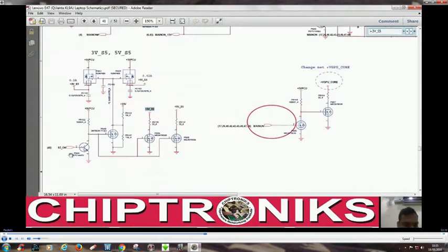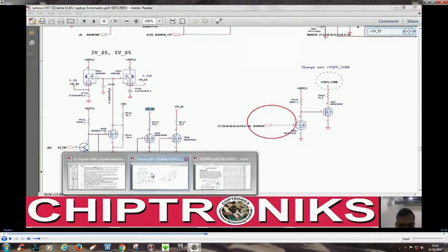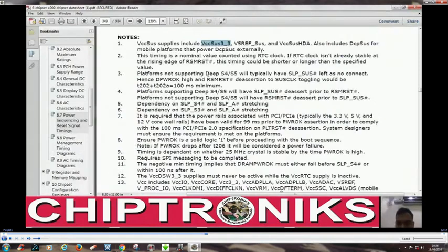And you can see this S5_ON, and as we have seen, this S5_ON is generated by the IO controller only when it gets SLP_SUS from the PCH. So this is the suspend power for the PCH. As we have discussed in a previous class, this is the suspend power of VCC_SUS.